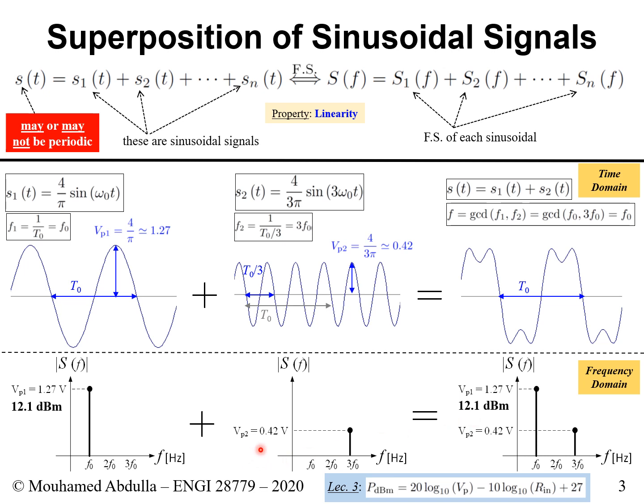And if we do it for the 0.42 volts, we enter 0.42 volts here, still with 50 ohms. We're still using the same spectrum analyzer device with an internal resistance of 50 ohms. We do the calculation, and this should give us 2.5 dBm. And that's it. So now we have a full circle of what we obtained by looking at the